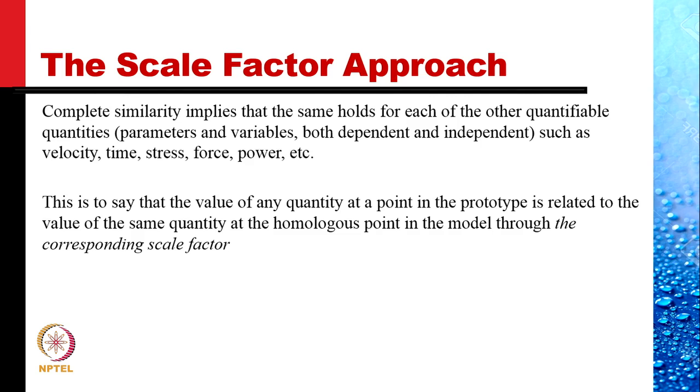This is to say that value of any quantity at a point in the prototype is related to the value of the same quantity at the homologous point in the model through the corresponding scale factor. There is a unique scale factor for a unique quantity. There would be a velocity scale factor, a time scale factor, a stress scale factor, a force scale factor, etc.